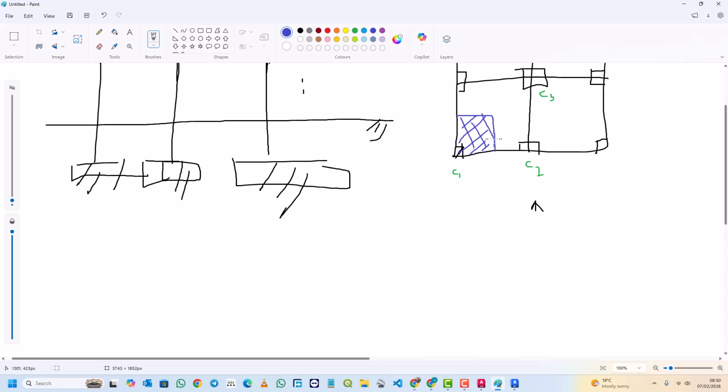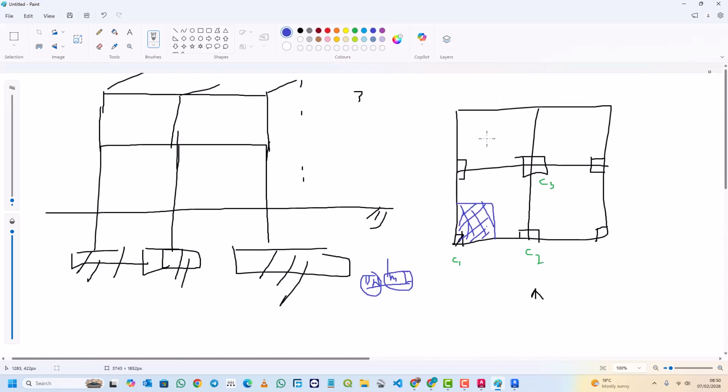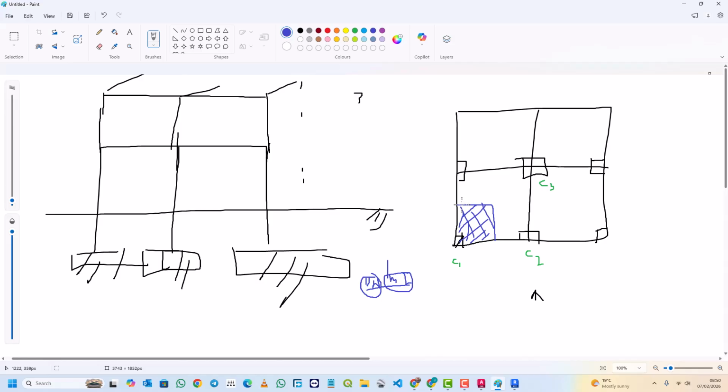Then after getting this area, we convert the slab load. Remember, slab load will be given in kilonewtons per meter squared. So you have to convert this kilonewton per meter squared into kilonewtons. So the best way to do this, you just multiply it by the area, and this area is this tributary area from the slab. And to get this tributary area method, you just use the supporting elements, that is the beams, and you divide them into half, and that will be okay with you.